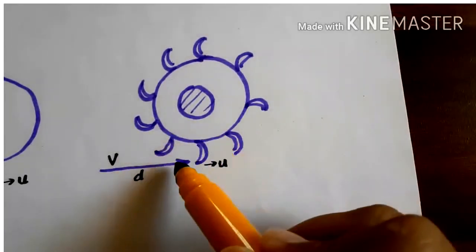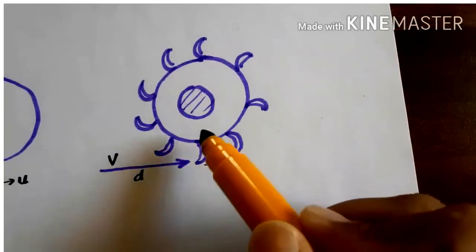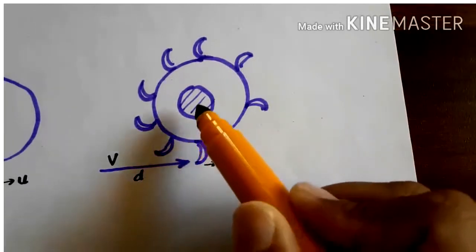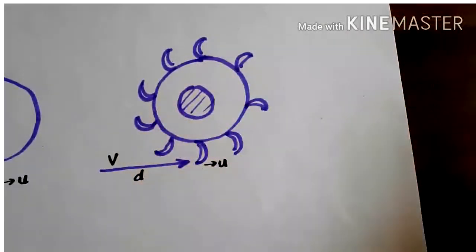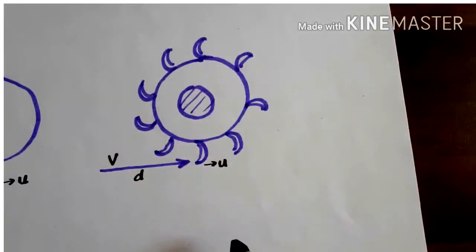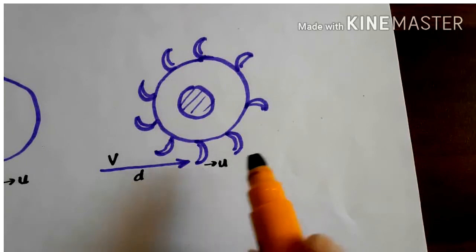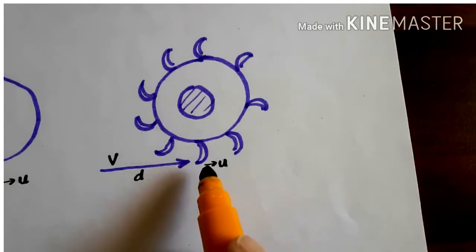So this will continue, hence the force, that is the energy, is being transferred from the vanes to the impeller, to the shaft, to the generator, hence the production of electricity will take place. So in this figure there is always one vane or the other facing the jet, and the entire fluid is being utilized here.